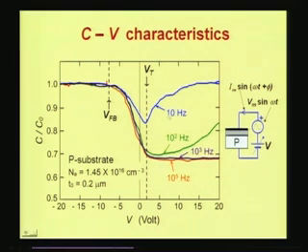Quasi-static means the frequency is very low, okay, 1 Hz or even less, because the frequency should tend to 0 for quasi-static operation. So such a capacitance versus voltage curve is difficult to measure at such low frequencies. So that is why you are not able to see that abrupt change going up behavior, but you see that the maximum capacitance in inversion is the same as the capacitance in accumulation. Here we have plotted C by C0. So since C is equal to C0, C by C0 is 1 in accumulation and in inversion.